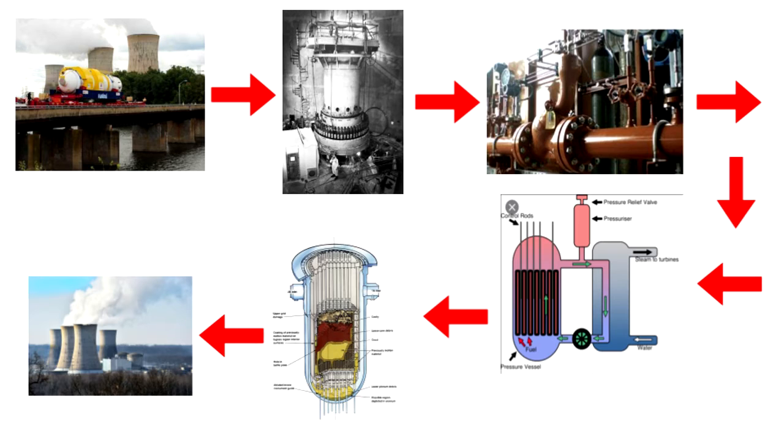At this point, the 3 emergency feed water pumps started, but an operator noticed that they were running, but did not notice that the feed water lines were closed, and the control panel had no light to indicate this. Despite the opening of the PORV, the pressure continued to rise. 9 seconds into the accident, the control rods automatically lowered as designed to halt the fission reaction.